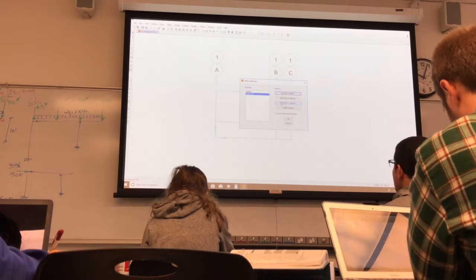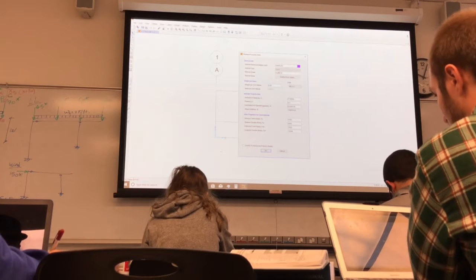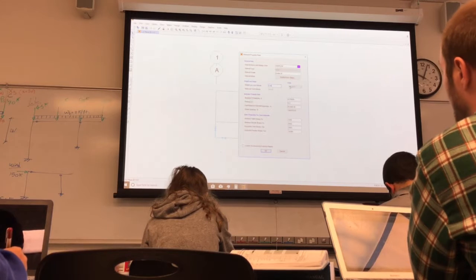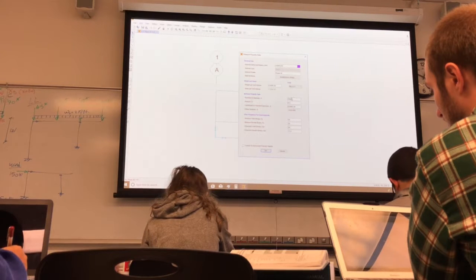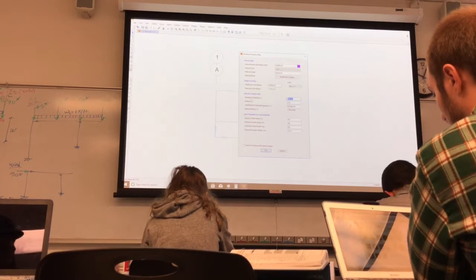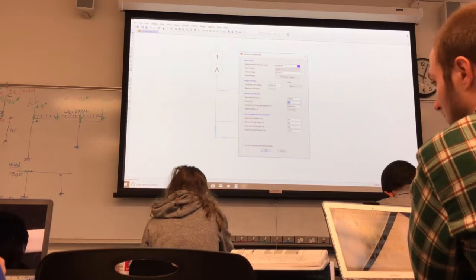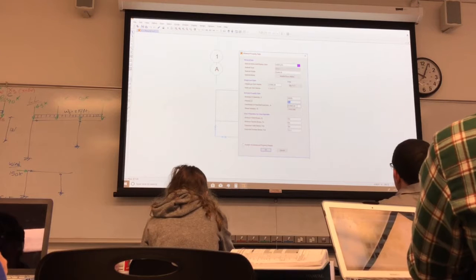Just maybe we need to look at it. As you can see, that's A992 grade 50. That's weight per unit volume. Maybe I need to change that to KSI. I can change that to KSI. So you see the elastic modulus of steel is 29,000 KSI. Poisson's ratio 0.3, and then that's thermal.